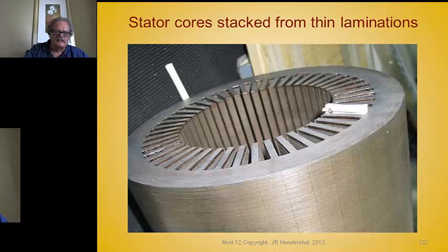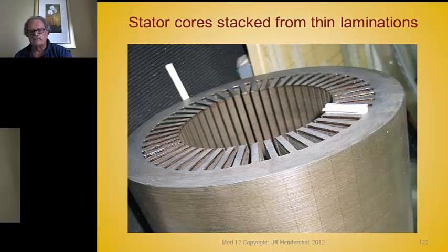This is a picture of a core that I showed on the last one, a close-up view. This one is stacked and bonded. Now I'm going to show you some pictures of a finger plate on the end of a stack, and this is a case where, in retrospect, I should have used a finger plate on this, because these teeth are very long. And yeah, they're bonded, but as it turned out, the bonding didn't take on all the teeth on the ends, and some of these actually stuck up a bit.